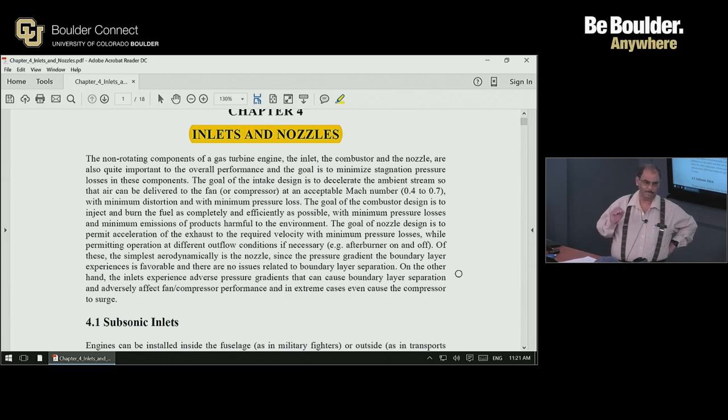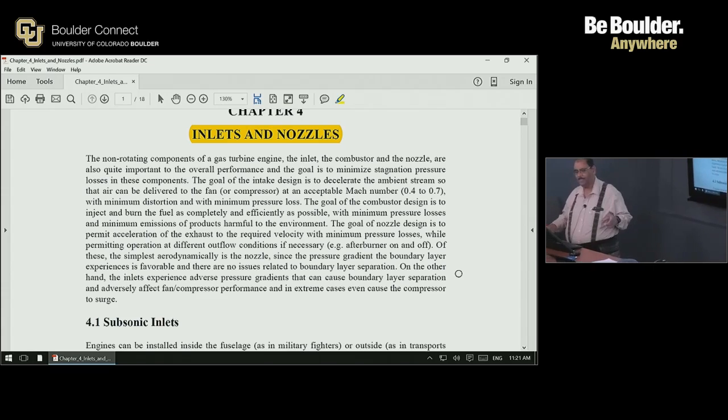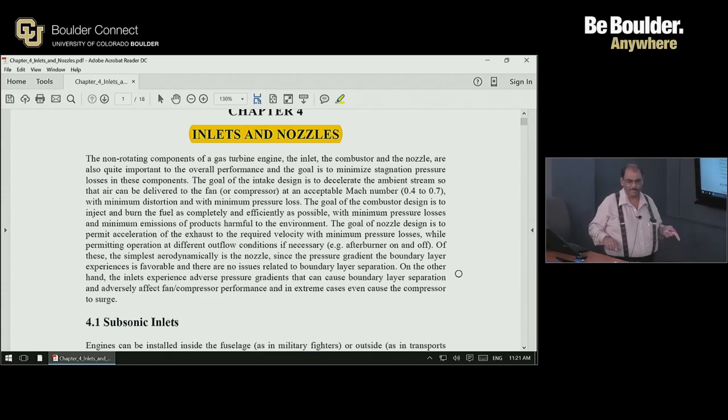Shock waves mean, of course, additional losses and therefore increased drag. So one has to make sure that the shock wave that terminates the supersonic region above the nacelle is as weak as possible. And that in turn limits what diameter of the nozzle you can select. Okay. That is for subsonic inlets.